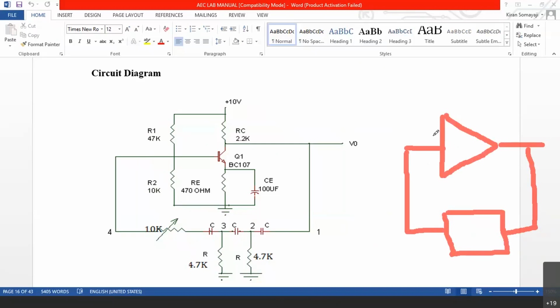Now, when we discuss an ideal amplifier, it will have a very high input impedance, very low output impedance, and the feedback network will introduce a 180-degree phase shift where it is CR, CR, CR. That is fine, but we are not dealing with an ideal amplifier. Our lab BJT amplifier is a practical amplifier. In the practical amplifier, you will have a ZI inside, right? You will have an input impedance, ZI or RI, inside the amplifier, then you will have an output impedance also.